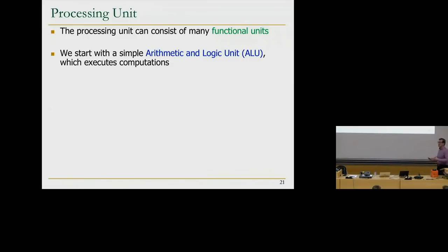It's called the arithmetic logic unit. So the arithmetic logic unit is essentially a unit that performs arithmetic operations and logical operations. It performs an add, for example. It performs a NOT or XOR. It depends on how you design it, of course. Underneath, you can design it to be very minimal. It could perform only one thing, but the programmer may write many things, and then you somehow make sure this works. Basically, in LC3, the arithmetic logic unit that you will see executes an add and NOT, and XOR also in LC3B, because that's a new instruction that was added.